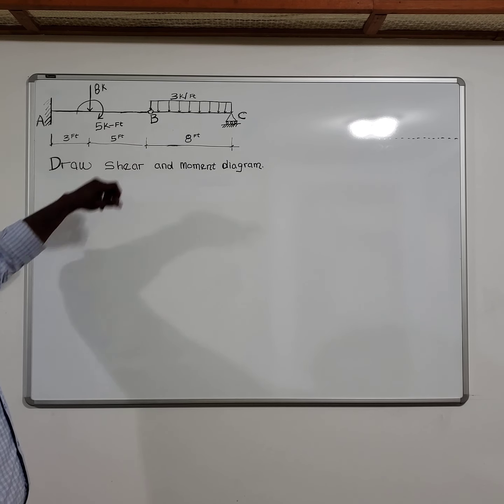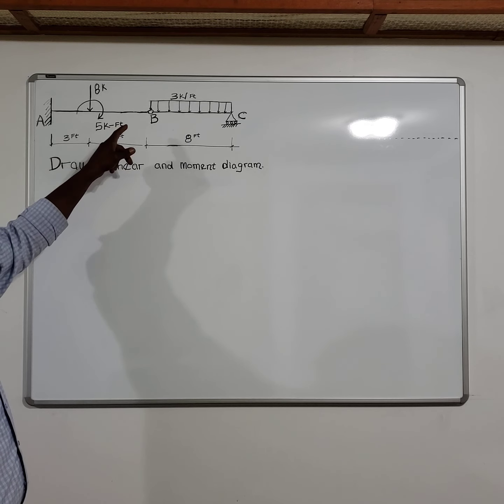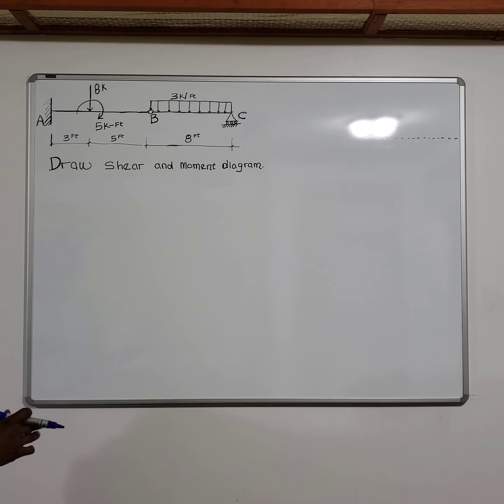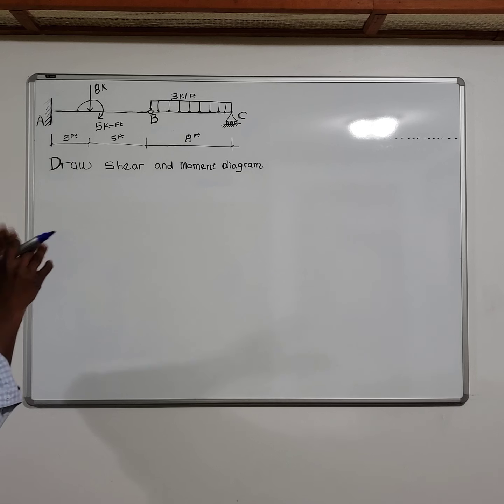it's a hinge connection. That point does not provide moment. As a result, you can divide this beam into two from point B. So you solve point A to B separately and point B to C separately, just to give you a background.